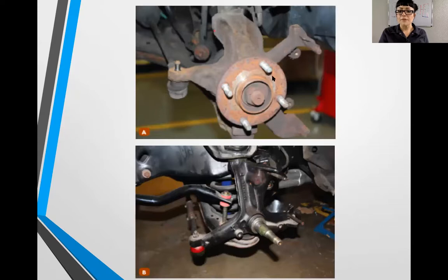Up here, I've got lug studs and a flat hub. Down here, I have no hub assembly, but I've got this piece that sticks out, like a rod. Here is the difference between top picture A and bottom picture B. Top picture A has the wheel hub. When I say wheel hub, I'm also referring to the wheel bearing assembly inside of it. So it actually uses a different type of bearing. And this piece can actually spin on the knuckle. My brakes and my tire and wheel assembly are going to attach to that, and I use my lug nuts.